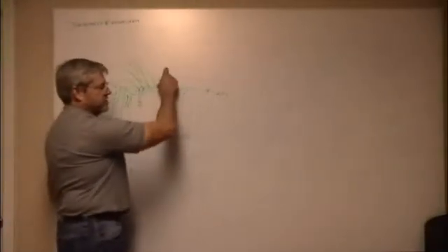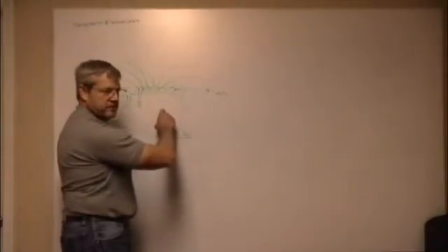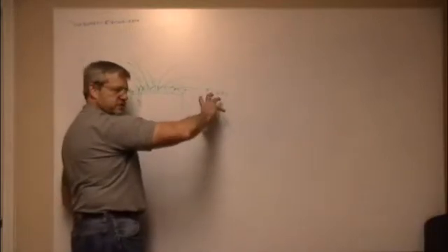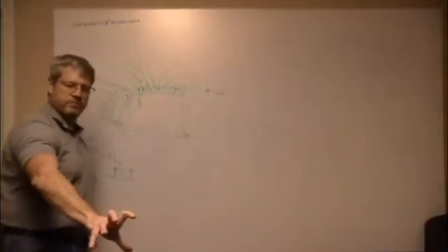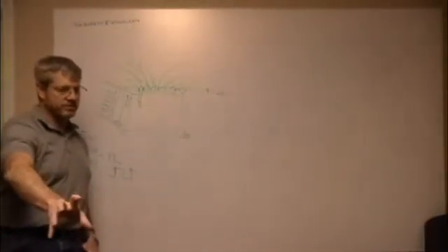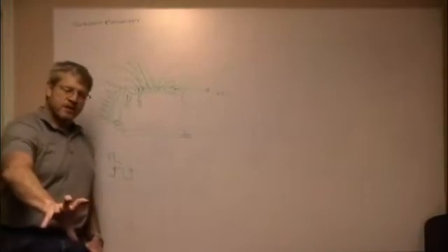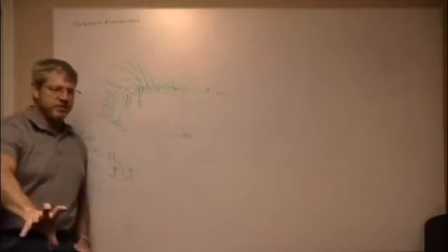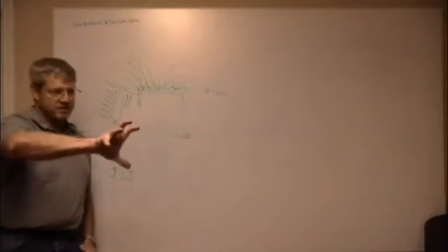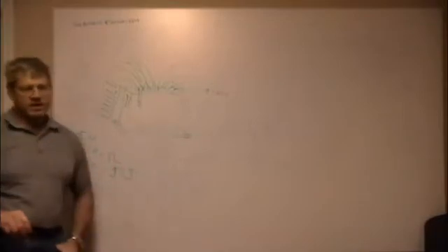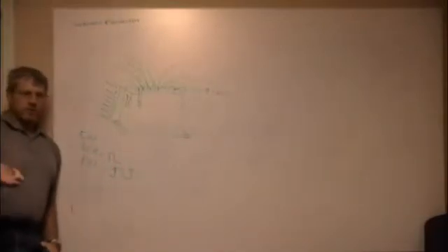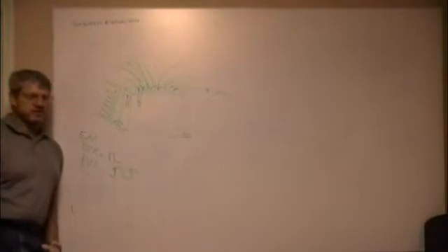And micro stepping, I could be wrong, but you remember how we talked about how I just turn this coil on and I turn this coil off, or I turn them both on and it chooses the position within a 1-step range, or maybe a half-step range. I think what they do is they PWM them and change the strength of the magnets. So you can choose 1-to-1, half step, quarter step, 16th step, I think all the way out to 64th of a step.